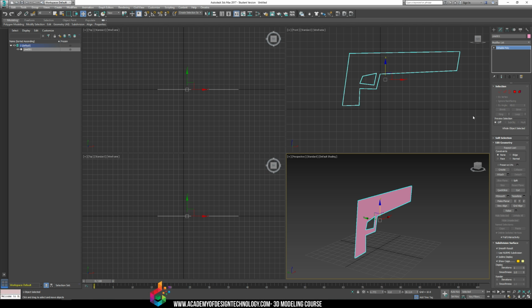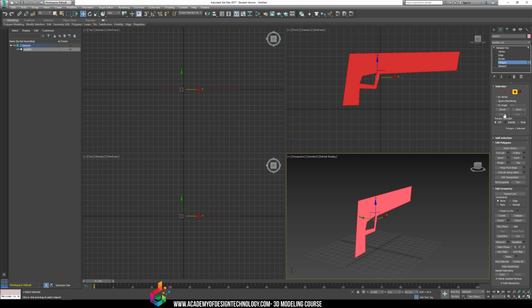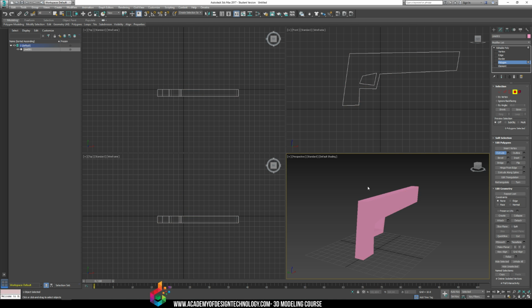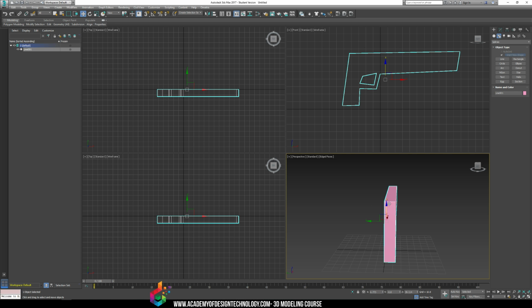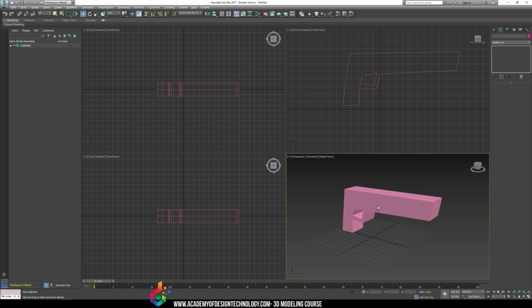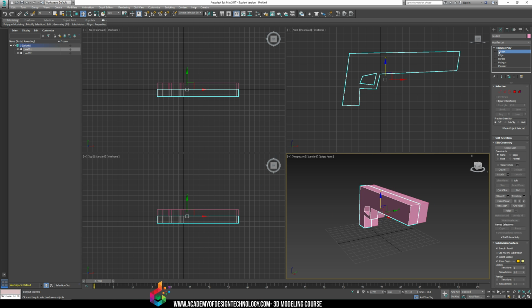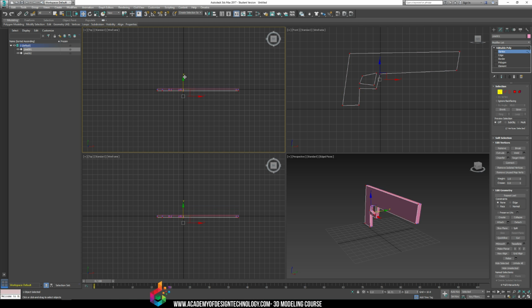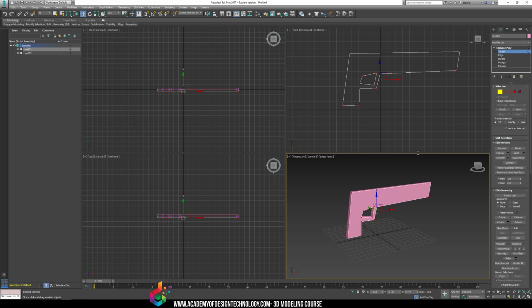And then remember, we have to extrude, copy one side to the other side, and then we're all good to go. If you want to make it a little easier, convert it to edit poly. The best thing to do is polygon, extrude, and then you can literally just mirror this and you'll be fine from the start. So I just grab that, I just extrude it, I go right to mirror, I mirror a reference, and there you go. Already set up for me. Everything's all good. I just have to change how thick my vertexes are. And then I have something I can work with. Then I can slice plane and do everything else I need.